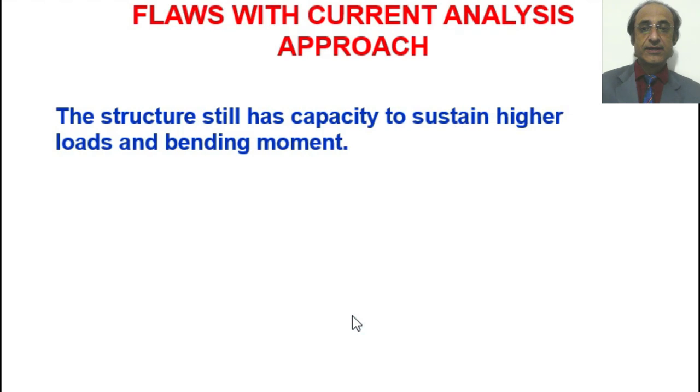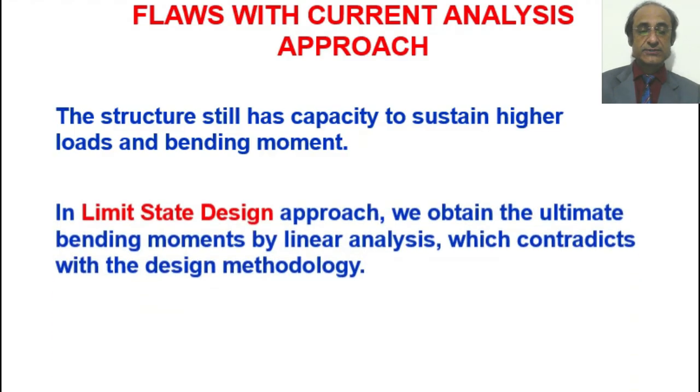But then in the limit state approach of design also, we have some flaws. The flaw is that although we are doing the design of the section very rigorously, taking into account the nonlinear behavior, we are relying on linearly elastic analysis to obtain the ultimate moments.